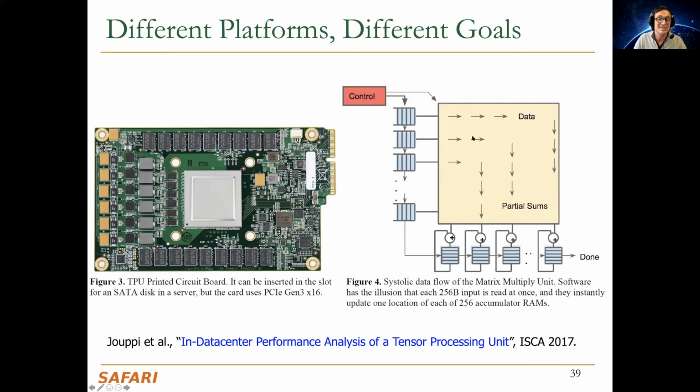That classification task is intensive in terms of multiply and accumulate operations, for example. And those classification tasks can be performed much faster using the specialized systolic array engine that essentially pumps data in and pumps outputs out over here and does multiplication inside this array while the data is flowing. We will cover the fundamental principles of this, but I wanted to give you this as an example of today's computing platforms that are specialized for machine learning. This is also one example of the algorithm-architecture-device co-design that I mentioned, cutting across these layers as opposed to just looking at the hardware-software interface and the microarchitecture.